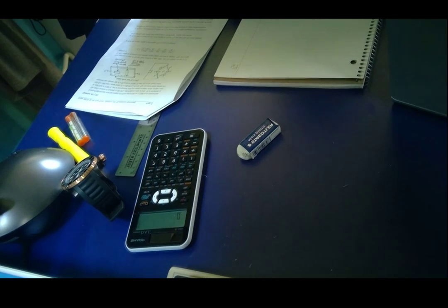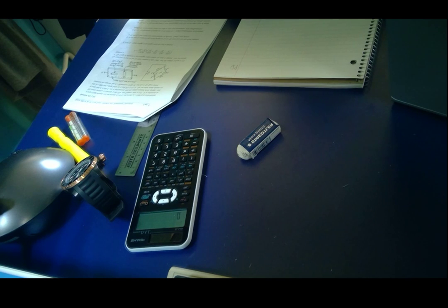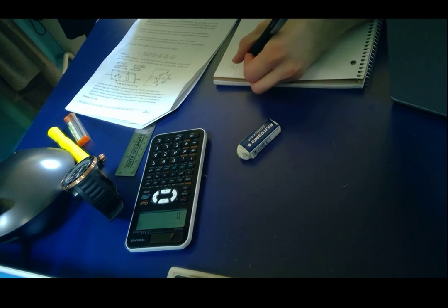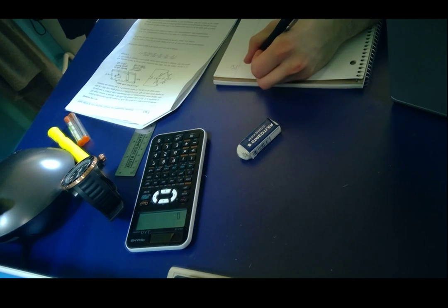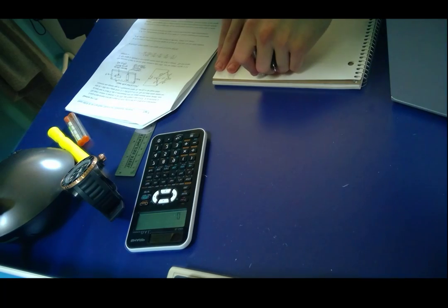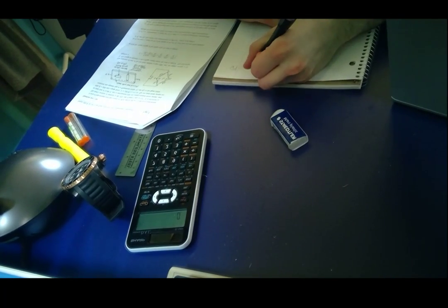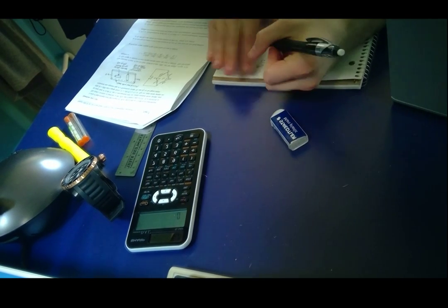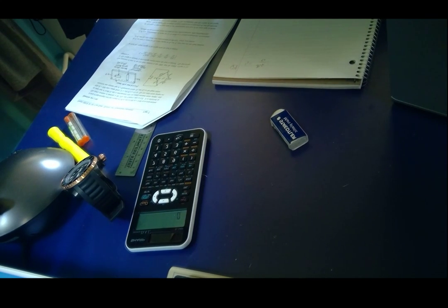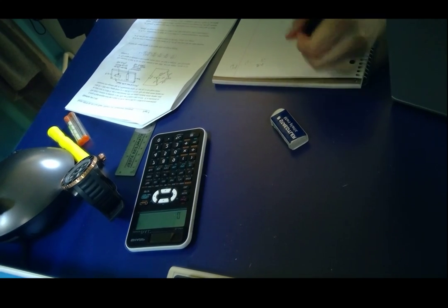Well, to know that, we'll have to know what the dR is. So we know that S, the strain gauge factor, is dR over R over the axial strain. Steel's modulus of elasticity is 200 gigapascals and Poisson's ratio is 0.27. Right.